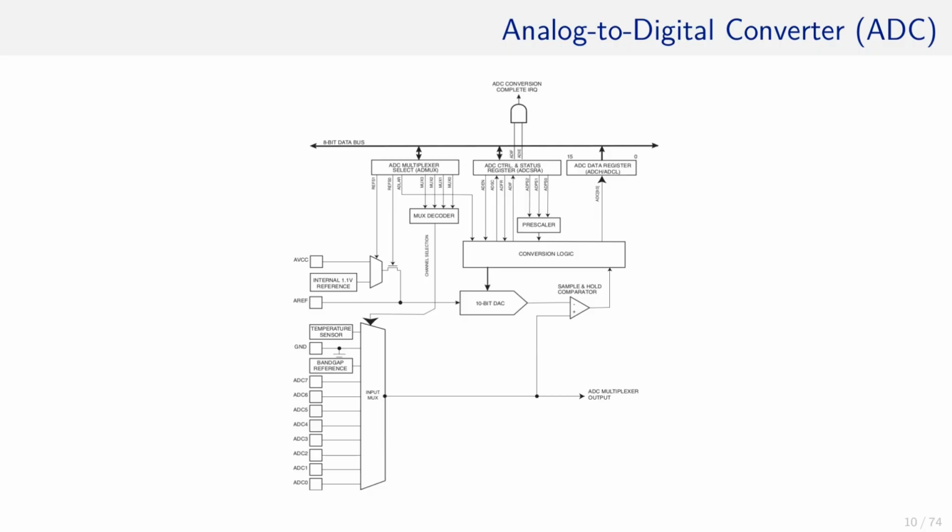The ADC can be tuned not only to increase the accuracy, but also its sampling speed, as we have seen in the previous chapters, in which the ADC was able to sample so fast that we had to set the UART transfer rate to 1 million bits per second to get the values out of the ATmega. That speed cannot be achieved using the Arduino library call.